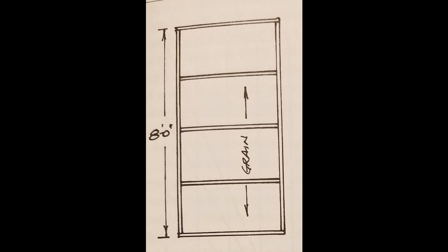Now, this is where we break down the actual structure. The walls and platforms, even though they're different in material type, are both built very similarly. The top and bottom boards are known as the rails, and then your 2 vertical pieces, at least in this image, are known as the stiles. All of the cross members that are in between are known as toggles.